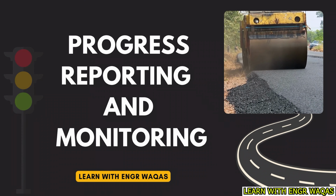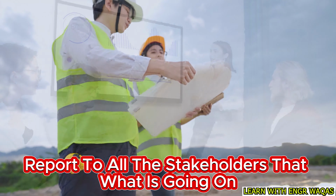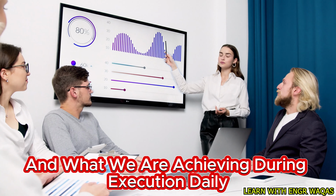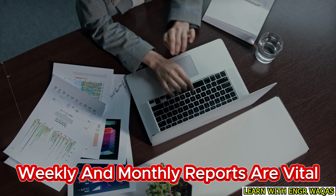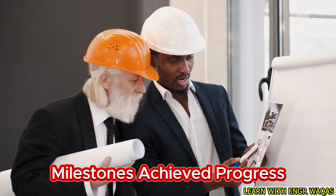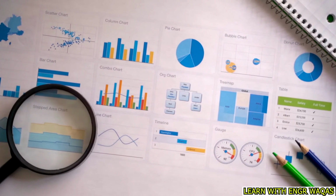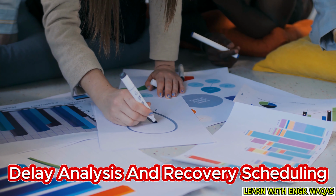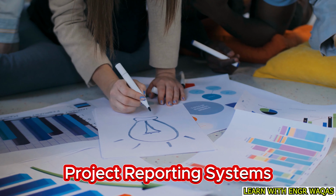Progress reporting and monitoring. Here come civil engineers. We as planning engineers are going to report to all the stakeholders what is going on, what was planned, and what we are achieving. During execution, daily, weekly and monthly reports are vital. You must show planned versus actual progress, milestones achieved, lab testing results, resource utilization, earned value management based progress reports, delay analysis, and recovery scheduling. All these things are part of our ongoing project tracking and reporting systems.